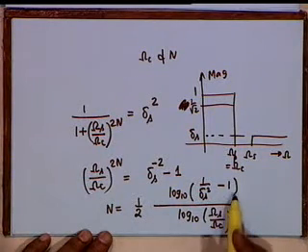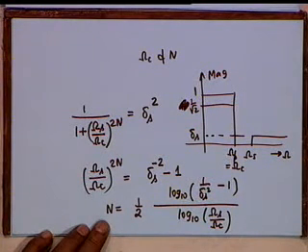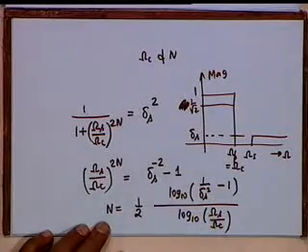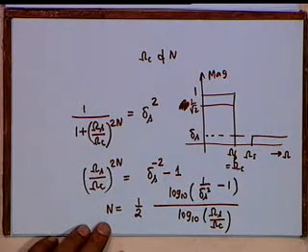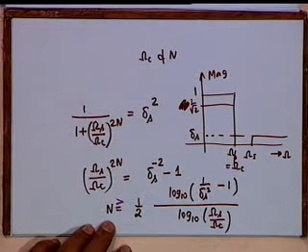Okay. Now, there is no guarantee that this quantity on the right shall be an integer, whereas capital N we require to be an integer, right, and therefore you shall choose an integer which is higher than this but closest to this. If this comes out as 6.7, then you have to use 7. Do not go for 8 because that unnecessarily increases the cost of the filter. Okay. And when you choose capital N greater than this, so let me make it clear, capital N to be chosen is greater than or equal to this.